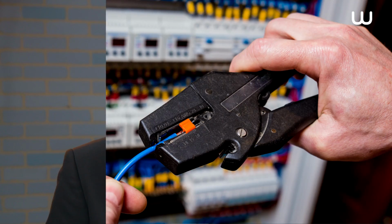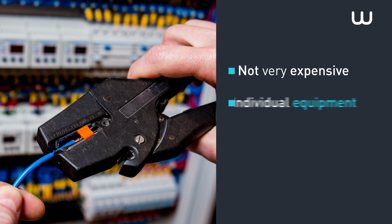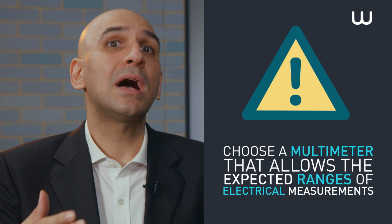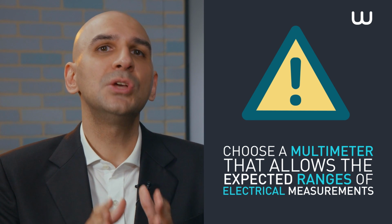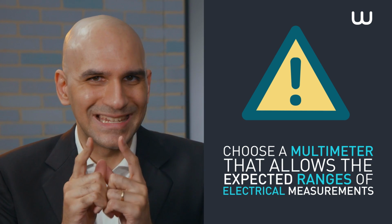The multimeter is a relatively cheap tool, and electromechanics can be individually equipped with these. It allows one-off measurements to be taken per parameter and per phase. The meter's accuracy depends on how much the device costs. Be careful to choose a multimeter that allows the expected ranges of electrical measurements at the sites to be correctly measured, in particular in regards to intensity.